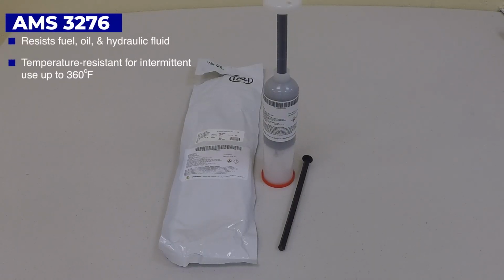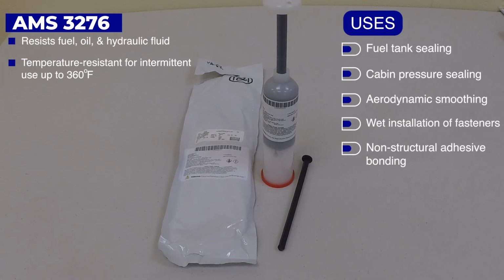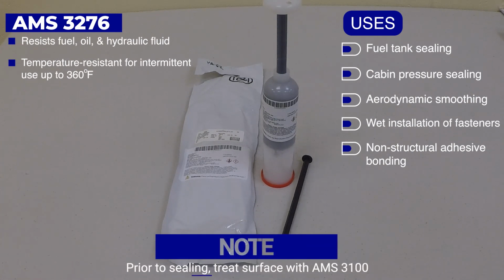AMS-3276, a sealing compound used on integral fuel tanks and general purpose up to 360 degrees Fahrenheit. Resists fuel, oil, and hydraulic fluid. Used for fuel tank sealing, cabin pressure sealing, aerodynamic smoothing, wet installation of fasteners, and non-structural adhesive bonding. Prior to sealing, treat bond surfaces with AMS-3100 adhesion promoter to enhance sealant adhesion. No corrosion inhibitors.